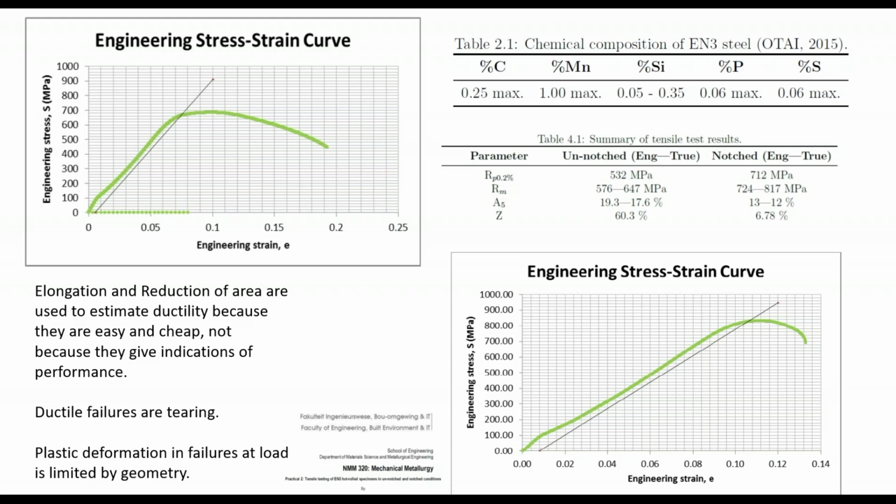And that's the reason in ASTM, if I look at a test bar and I see that at the fracture it has visible porosity or inclusions, I don't count that test bar. I throw it away and get another one, because I'm actually testing to make sure that the steel has the quality I want, not that the test bar has the soundness. And so I'm really testing the material properties.